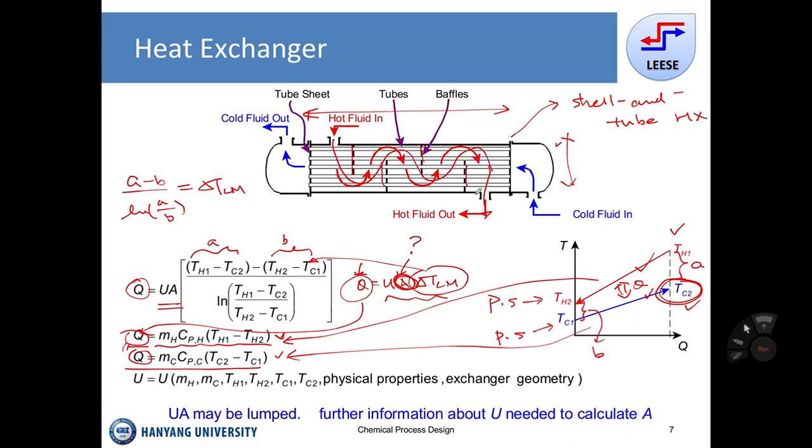So based on the choice of the number of tubes and the diameter of the tube, and looking at that side, you might arrange the tubes in a rectangular position, or you might want to place them in a triangular position. Based on the configuration of the tube arrangement, the amount of Q is different.